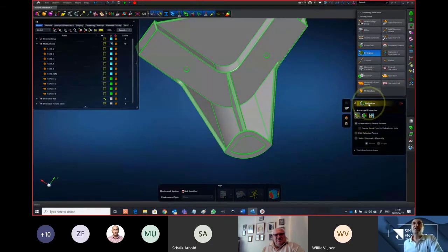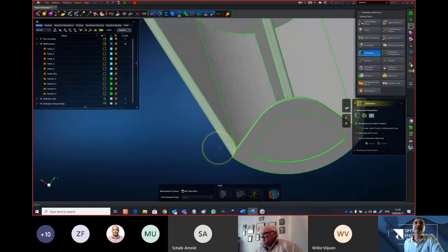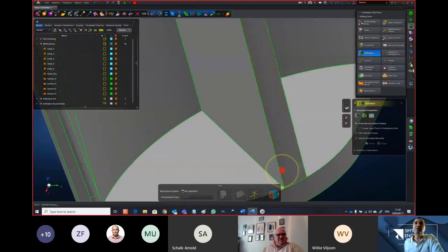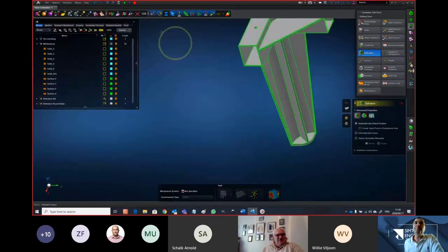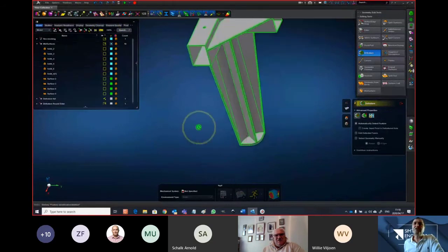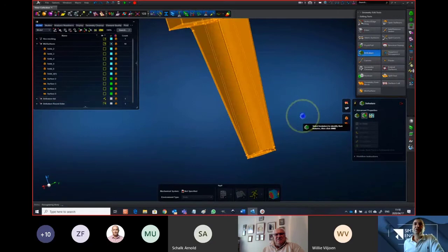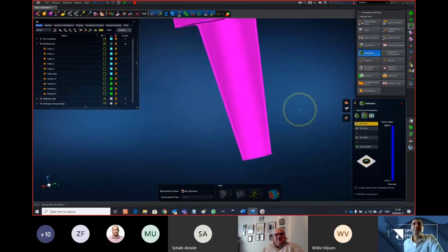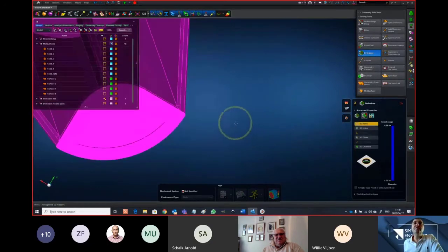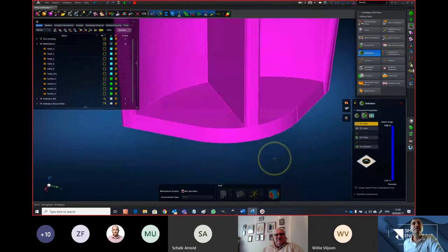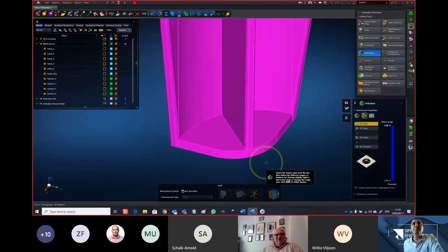So you know that in the defeaturing tool, we also have different options. The first one is basically a case-by-case option where you just pick one surface at a time, and it defeatures it. The middle one is the one that I wanted to use in this case, purely to defeature these fillets so that it's in a more appropriate shape for hex meshing purposes, so that I don't have as many elements.